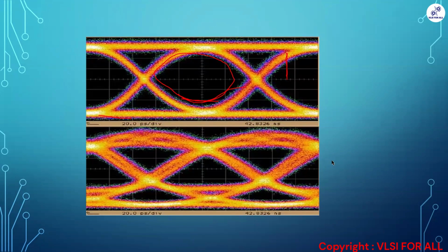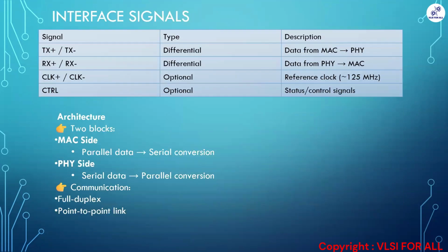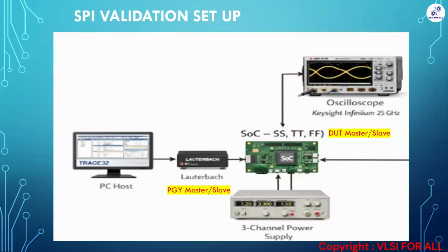So you have to convert that C file into a CMM script. That CMM script is used to load and run the test case. In Trace32, we can't give the C application directly. We'll be using that CMM script and running the corresponding test case. Okay.